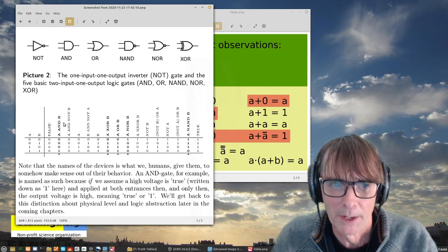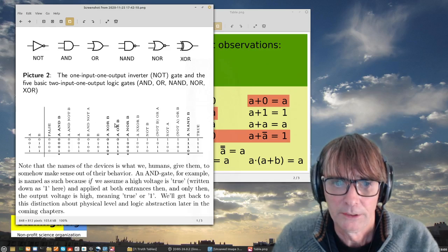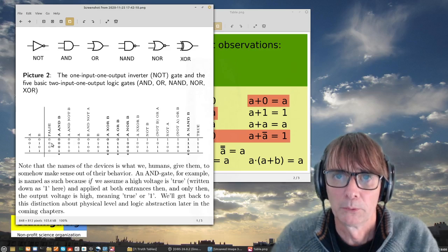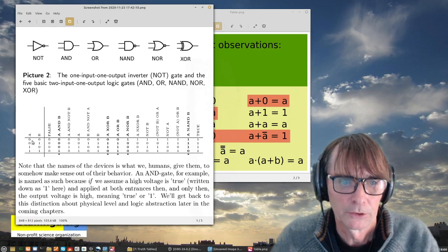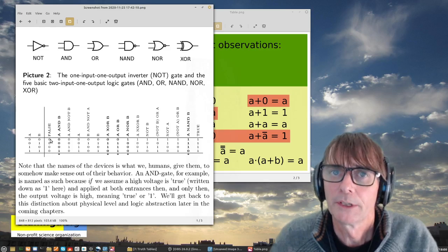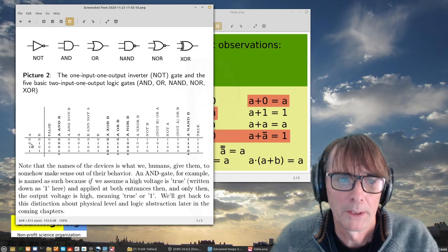So how many different gates can you make? That would be actually 16, because I just write down here all possible output combinations. So I write for 0, 0, that can be 0. 0, 1 will be 0. 1, 0 will be 0. 1, 1 will be 0. So it will always be 0. That is a combination. It's possible. So it will always be 0, independent of A.